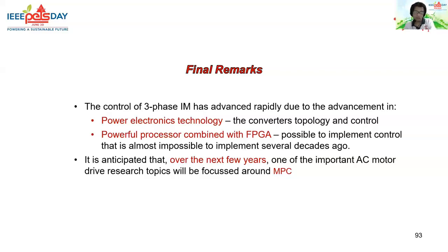For example, MPC, which was previously limited to slow process systems, can now be implemented in very fast processing systems with smaller time constants, such as power electronic systems. It is anticipated that for motor drive applications, over the next few years, the research is going to be focused mainly around MPC, which is model predictive control.